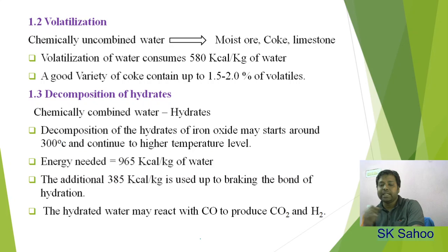Also, water is deliberately added to decrease the dust loss in the top gas from the ore fines. We generally know that there is no chance of adding iron ore fines as a raw material inside the blast furnace, because it is operated at high temperature, and due to the high velocity of gas there will be dust nuisance, and that will increase the load on the gas cleaning system of a blast furnace.